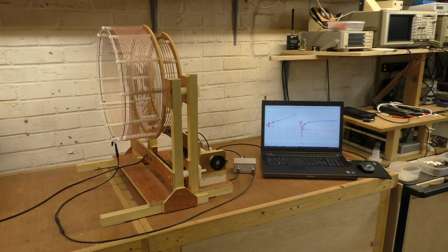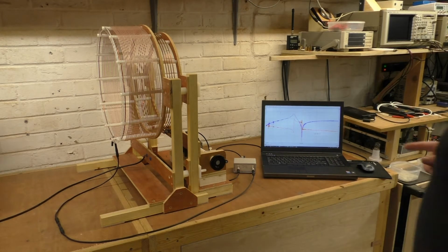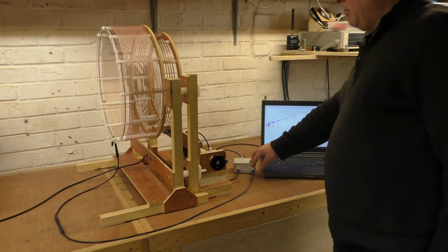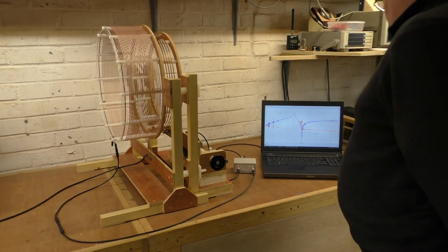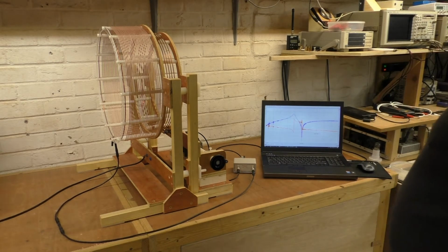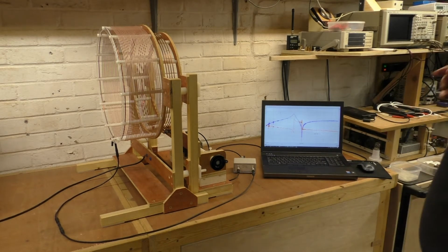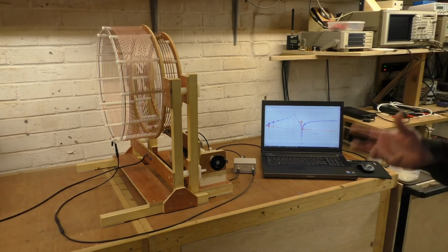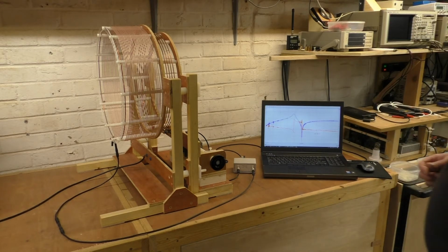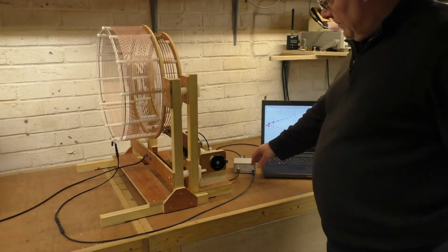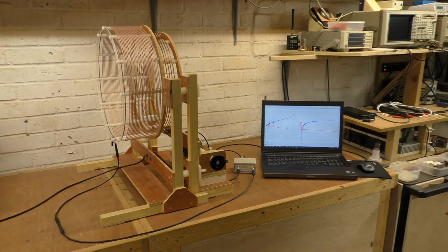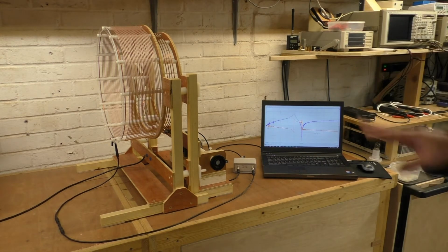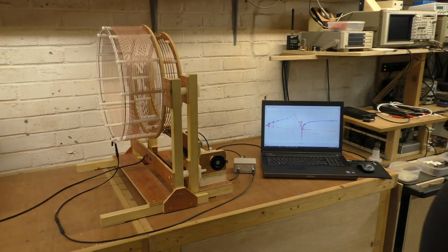And of course what that's going to do is load the coil. This is nominally a 50 ohm input impedance over the band that we're looking at. We're going to be looking here at 500 kilocycles up to 5 megacycles, which is a normal band that I do these measurements over. And if I attach that to the copper, it's going to load the output of the coil. And that's obviously going to reduce its resonant frequency.